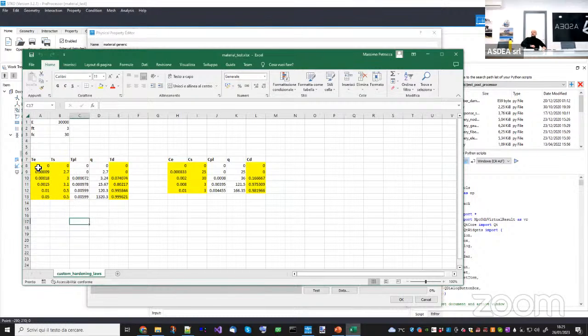So let's say that the first part of my tensile behavior is like the one of the model code. So my peak will be FT. Then this one will be 0.9 FT. So let's place this point here. So this one will be the strain at this one. So the behavior up to here is elastic, so 2.7 divided by the Young modulus. And this one will be twice this value. So I input these values here in my